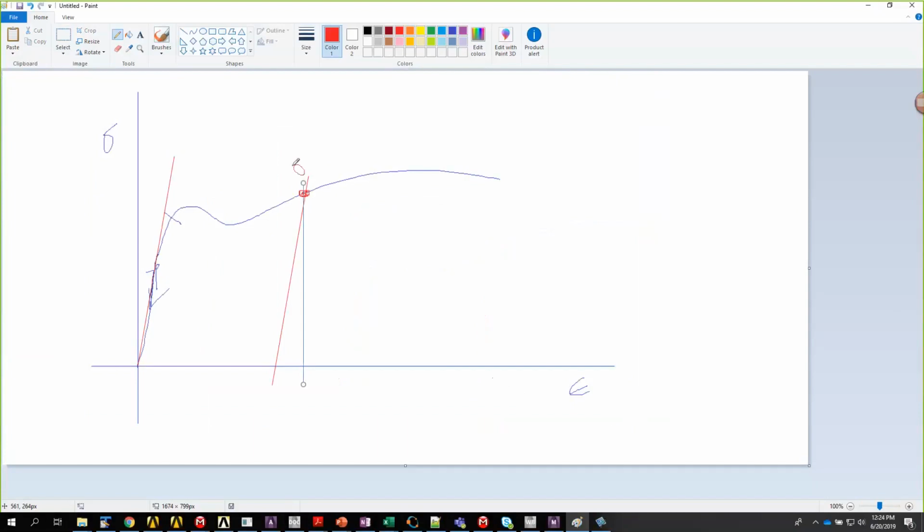This is the stress at a particular instant. This is the strain, the total strain at that particular instant, corresponding to that stress, which is elastic strain plus plastic strain. This portion is elastic. This portion is plastic. So you cannot say the strain that corresponds to a particular stress is totally plastic. There is a component of elastic. You need to subtract that component.